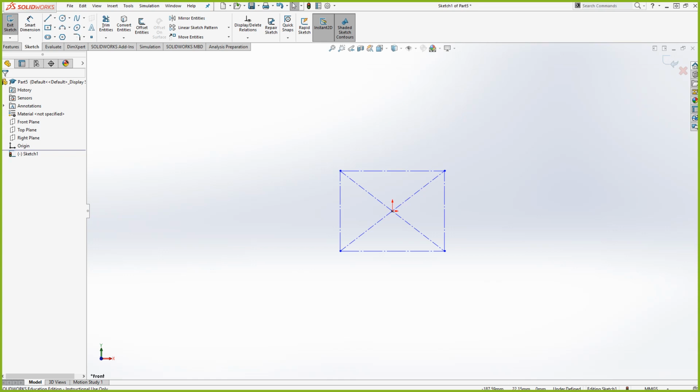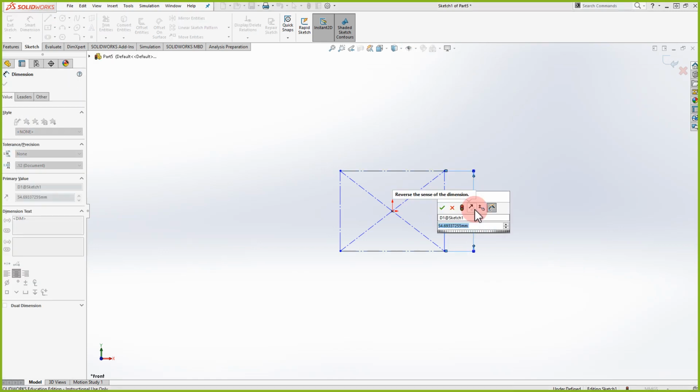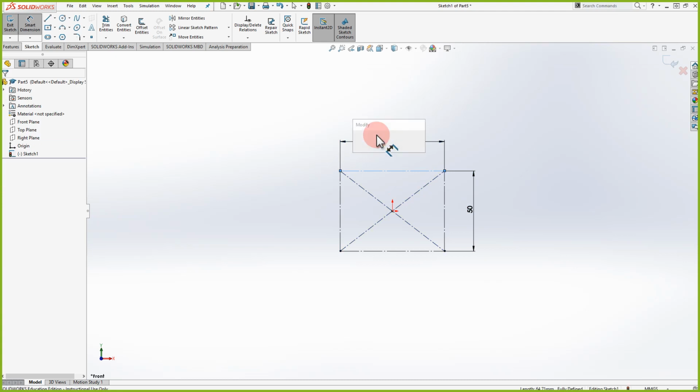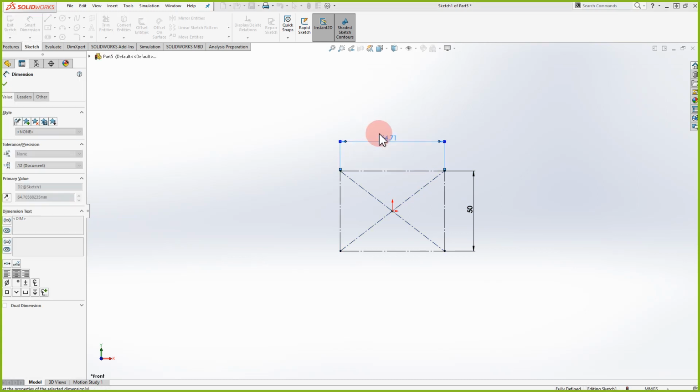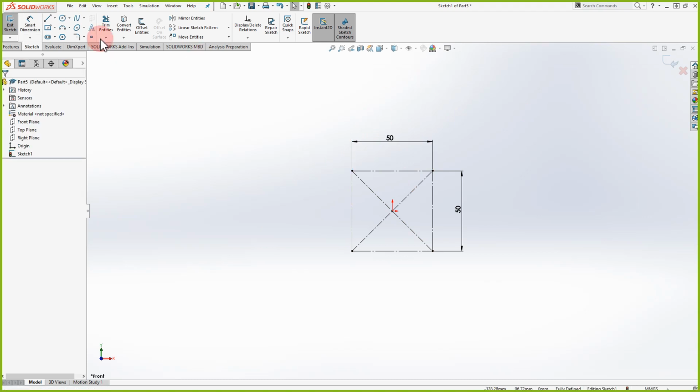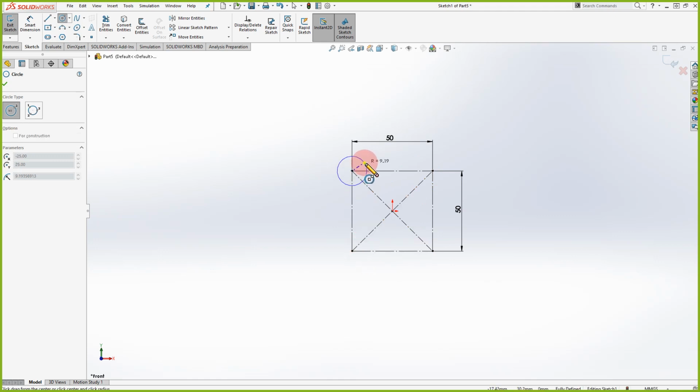So now let's make this cube. Let's add our dimensions quickly. We can use this, for example, if we were placing holes and we needed them to be 50 and 50 apart. We have our reference line here, and all we need to do is make our circles based off that. So see, we made our construction lines. Now we could just make our circle there, another one here.